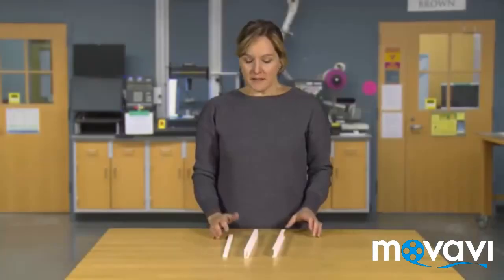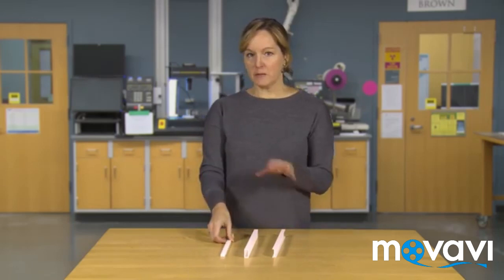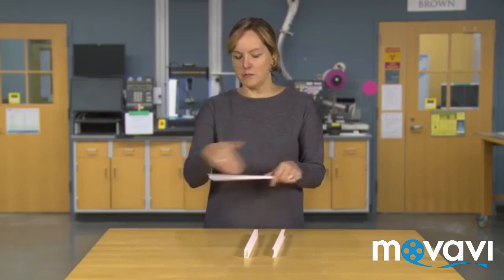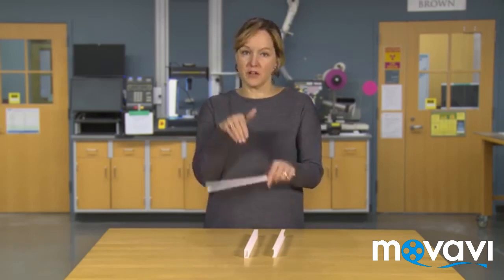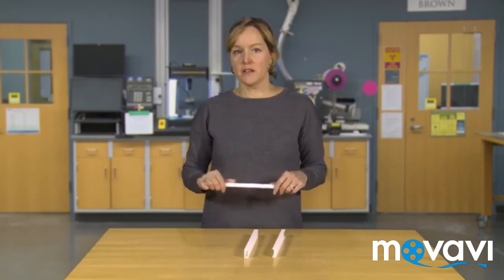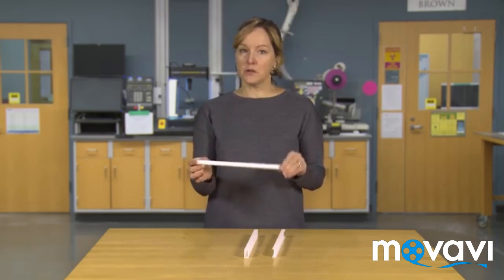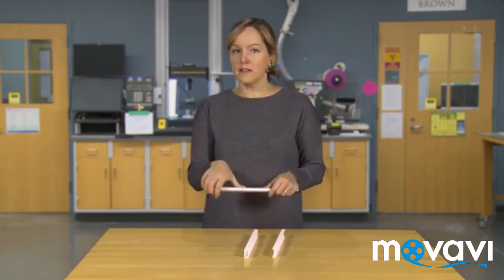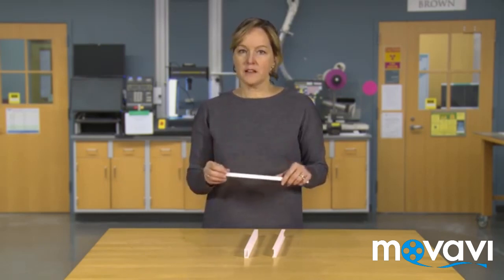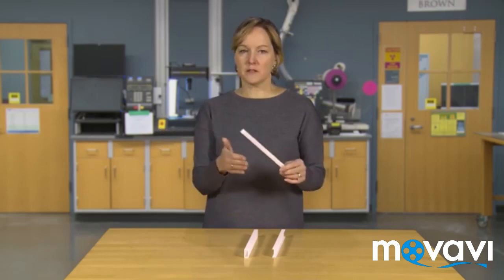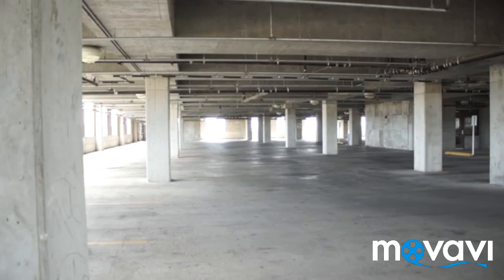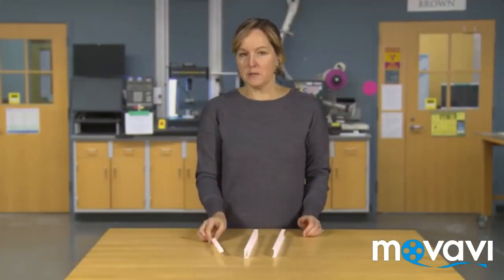So, shear versus bending. When we talked about these, we talked about there being possible shear versus bending. A beam has to resist both the vertical forces, which cause shearing, and then a bending behavior. Most beams, if they're long and slender, will fail in bending. So they'll reach their tensile or compressive capacity before they shear apart. The exception would be a very short, deep beam. Sometimes, say in parking garages, when we get really deep concrete beams that are fairly short, they could have issues with shear. But in this course, we'll focus primarily on the bending behavior.